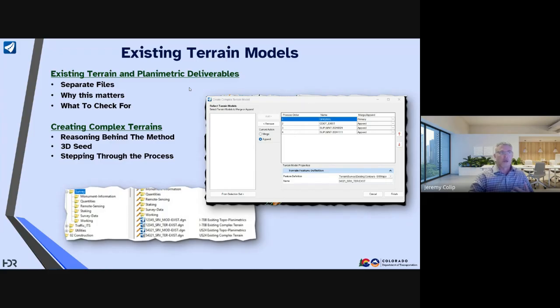For instance, if I keep getting information in a terrain file and I have to update that terrain file and the planimetrics at the same time, I'll have to save that as an updated file. Then all of a sudden, a lot of my drainage elements will be disconnected. Corridors are disconnected. There's a lot of rework that has to be done.